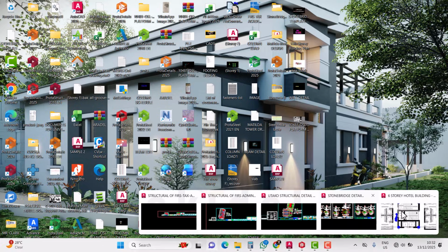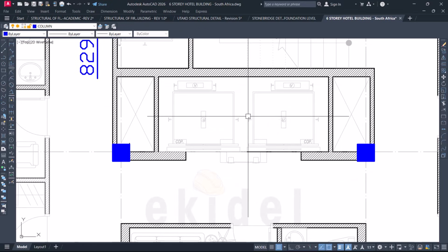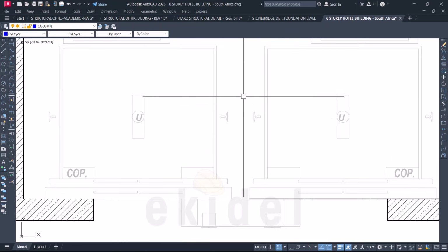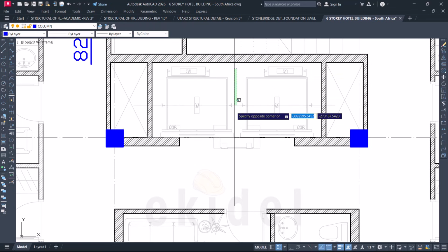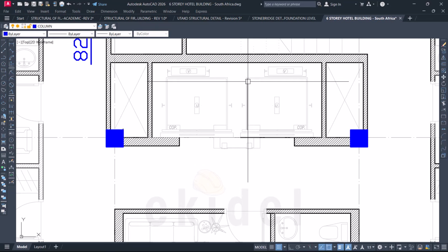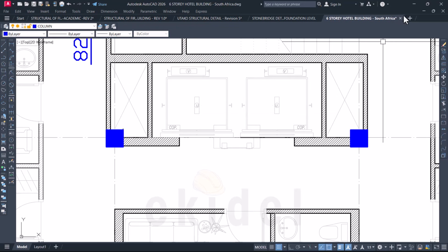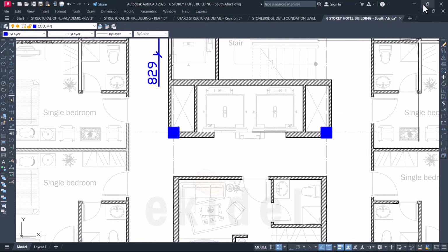Now from the CAD file, you can see that there is no wall here. So basically these lifts are standing lifts. So they don't need to anchor on the wall on this edge. Alright. So this is a freestanding lift or double lift that comes together as a double lift. Okay, that is fine. Else we would have added a wall here to provide an anchor for this lift side here and this lift side here. But in this case, we don't need that. Okay, that is fine. So we have now created the opening for the lift.